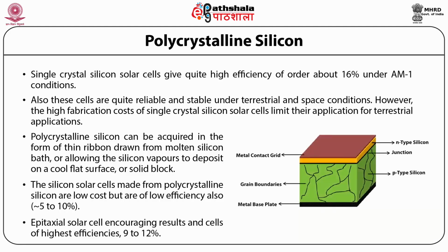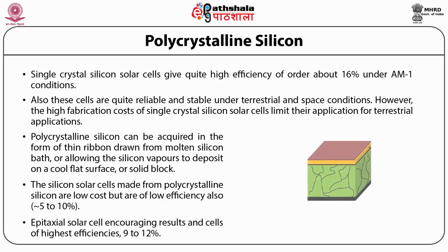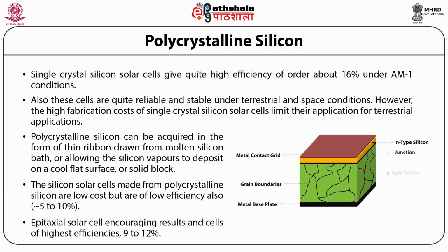In the conducting oxide insulator semiconductor cells, a window semiconductor is used over an active semiconductor substrate. This thin film oxide window, which has high transmittance for solar cell radiations and high electrical conductivity, acts as the anti-reflective coating.